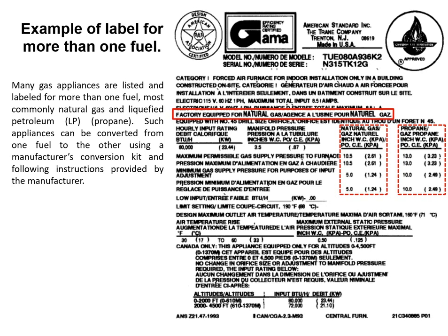So the appliance label gives us good information on exactly what type of fuel can be provided for this particular application. The installer must note, and the inspector must note, that the factory equipped fuel in this case is natural gas. If we wanted to do a conversion, we would probably locate the manufacturer's installation instructions and find out exactly how to properly convert from natural gas to propane.